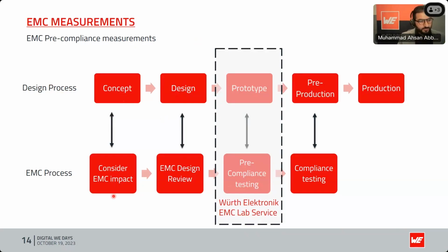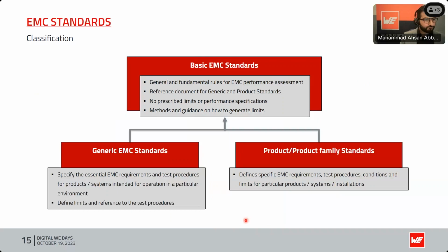After the concept and design, you consider EMC in the initial stage of the design, from the directive and legislation point of view as well, and your design reviews include the EMC point. Then when you have your first prototype, you want to perform some pre-compliance measurement in a pre-compliance lab to save cost and have an initial idea of where your product lies with respect to the standards. Then you move towards a fully compliant lab in a pre-production stage before going for series production. So this is the area in your prototype during your development stage. We want to support you with pre-compliance measurement, not only measurement but also troubleshooting and optimization. And we have 2 labs in Waldenberg and Munich for this purpose.